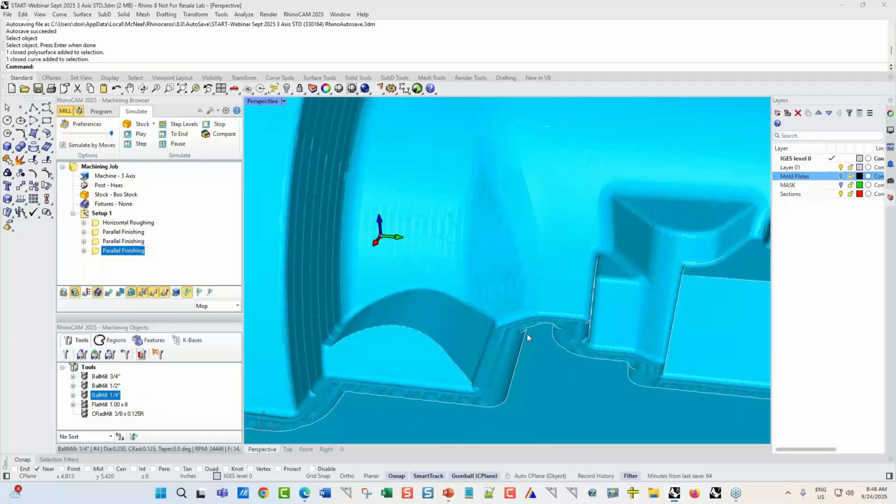Because if you think about it, these contoured surfaces, they're not vertical. This draft on these, you have a draft here. This one here might be vertical, but then you have the curved ones, which are not vertical. So this fillet is really a bitangent arc.